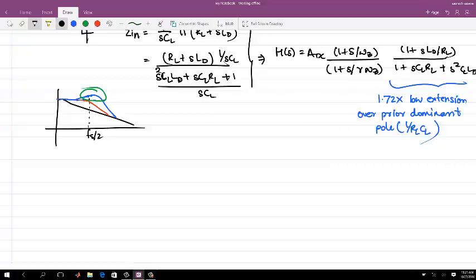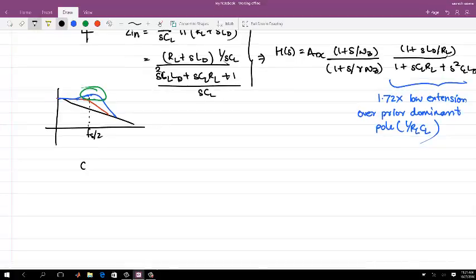As the concluding remarks on CTLE, we have that your output pole, if you are not using an inductor because of the area, you are limited in your peaking frequency because of the common mode output voltage, current and RL, right?